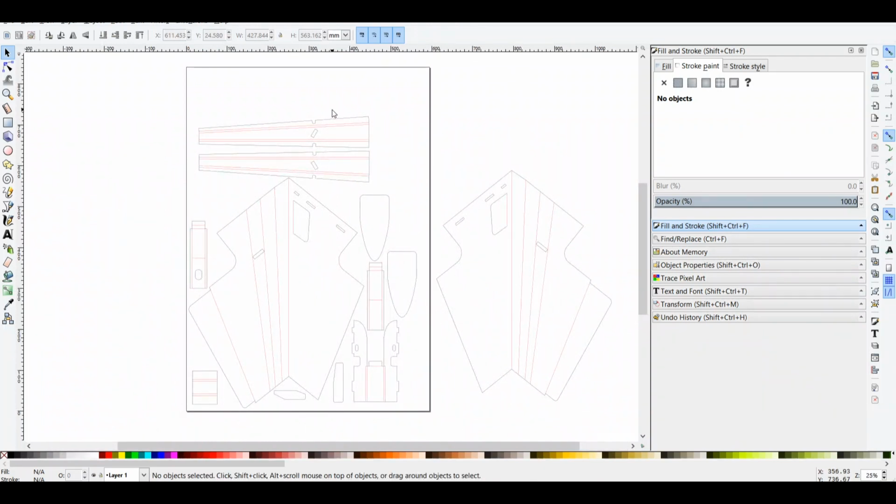The main wing won't fit, and then there is extra space here. So after you cut the foam board, you don't throw it. You can use the uncut remaining area as a spare, and then in the future you can just create a single part, generate G code, and then move your cutter head over to this side and start cutting, fully utilizing the remaining space.